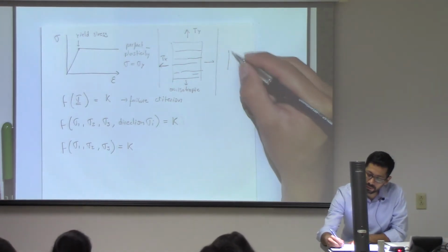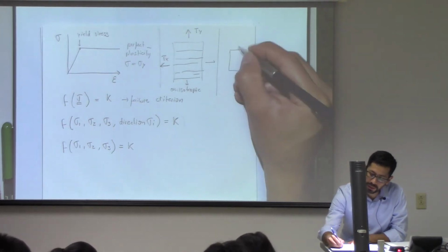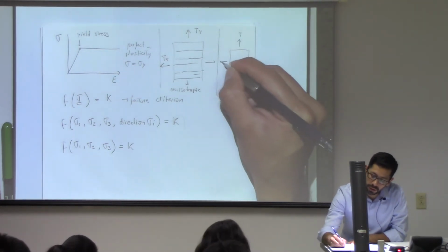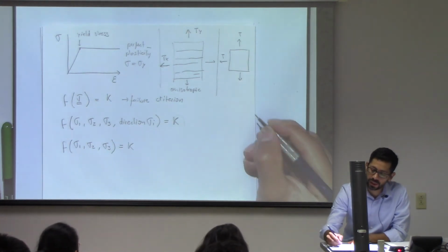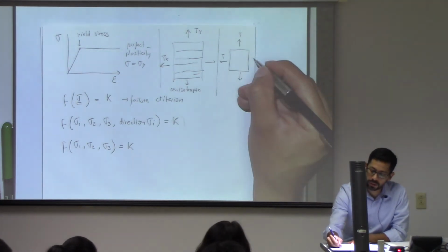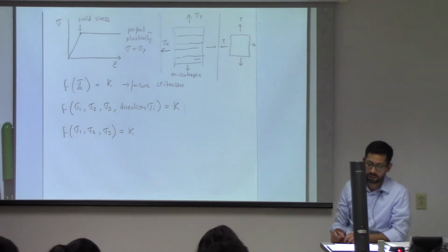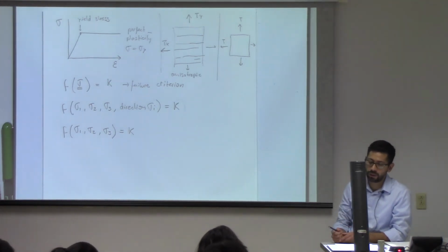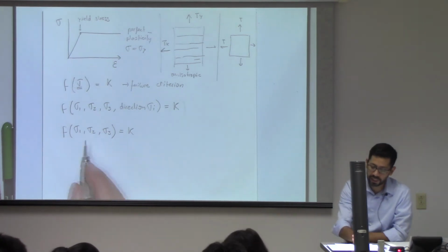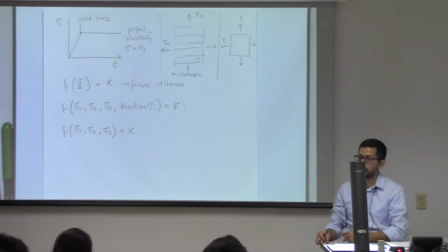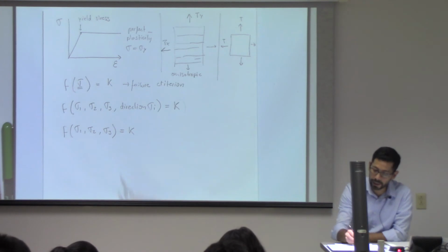But if you have an isotropic material, where you assume, for example, that the tensile strength is the same in all directions, then we can write a shear or tensile failure criterion, or a failure criterion in general, just in terms of the principal stresses, only by assuming there is isotropy, okay?